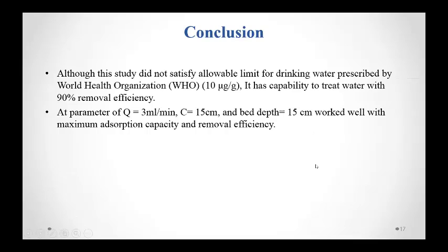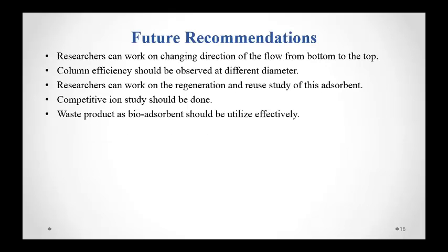In the conclusion, although this study did not satisfy the allowable limit for drinking water prescribed by the World Health Organization, it has the capability to treat water with 90% removal efficiency. At these parameters, with a flow rate of 3 ml per minute, concentration of 3 milligram per gram, and bed depth of 15 centimeter, it worked well, and maximum adsorption capacity and maximum removal efficiency were observed.